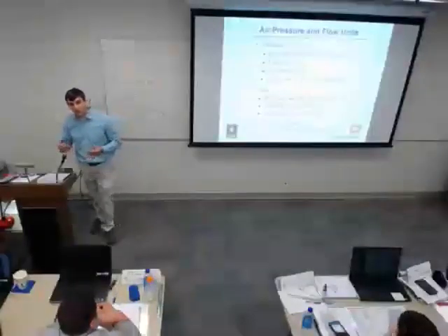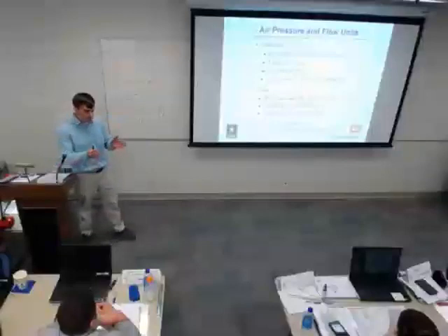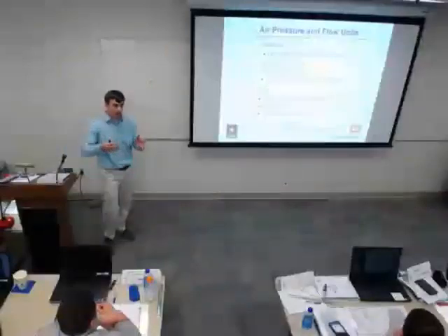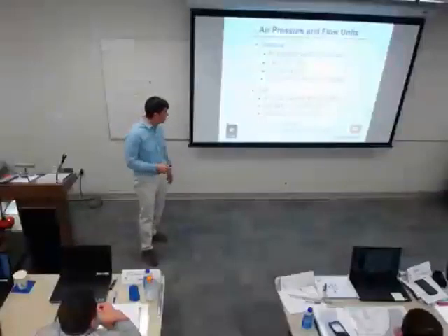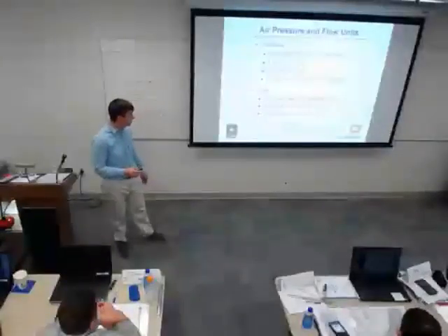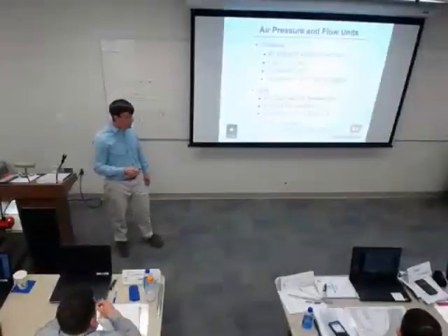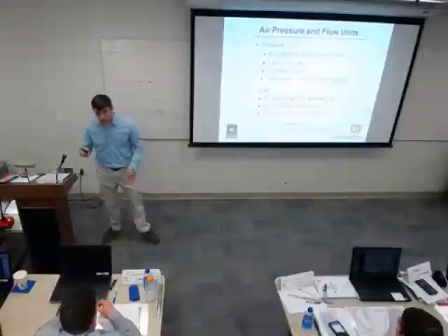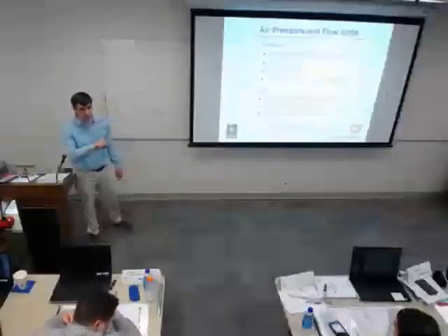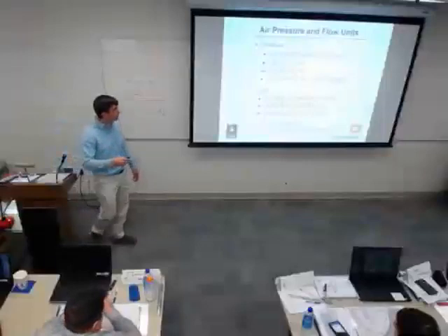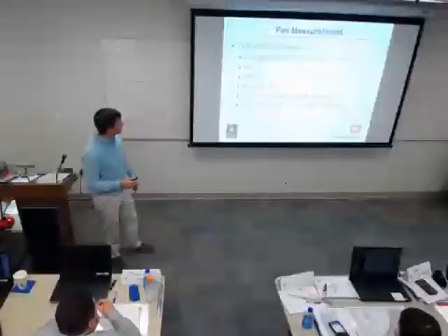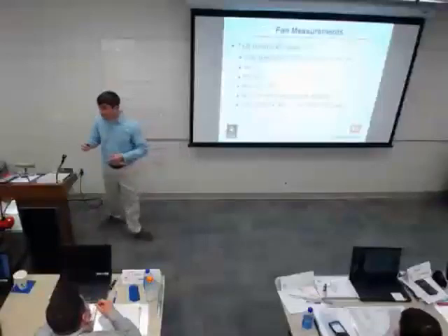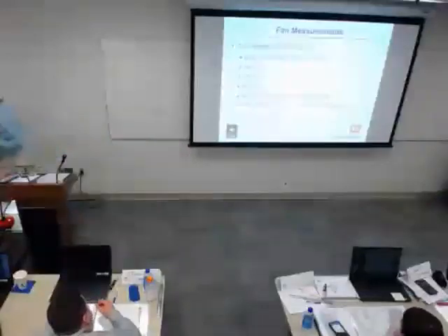For airflow, we're talking about cubic feet per minute, and you can correlate that to water flow. That would be the equivalent of gallons per minute. We're actually moving a cubic foot of air in 1 minute. That would be liters per second in SI units. Again, I've had one job where they were published in SI units, and we went through and wrote every single dimension back in English units just so we could build it.